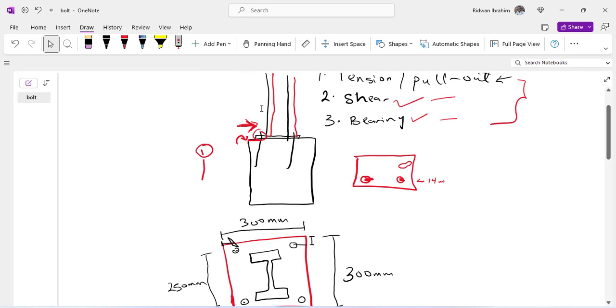As explained earlier, what pullout means is when this bolt is going up, something pushes it up. If this bolt pushes up, that means this one will come down. That is when you apply a moment. You can just imagine you try to twist this column. So this side we try to go up and this side we try to come down.